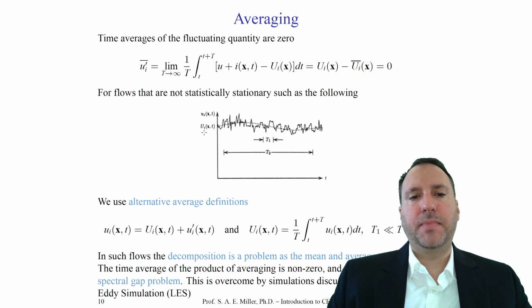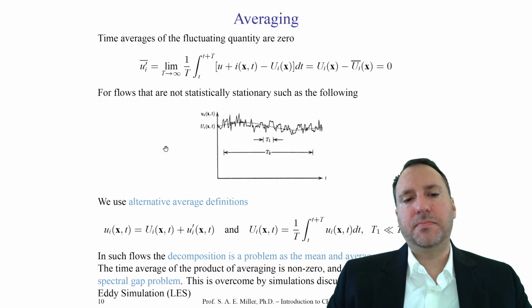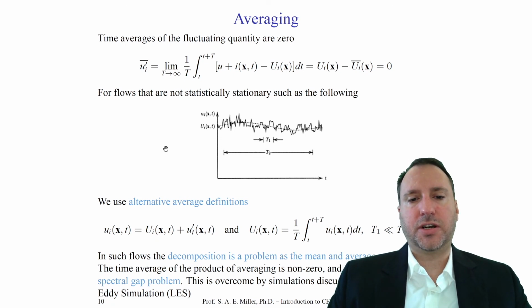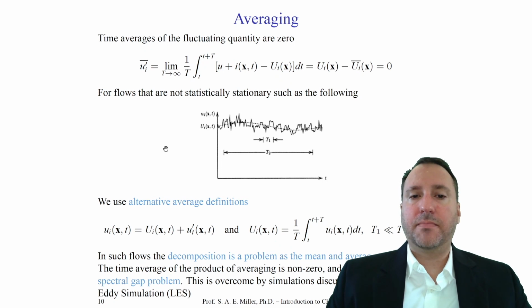And we can find a mean value. This is almost like a short time history mean. So the mean value about this type of flow here is higher than at a later time. And so the mean is changing with time. This means, unfortunately, that the flow is not truly statistically stationary. And that might be okay. We still can actually use this approach.